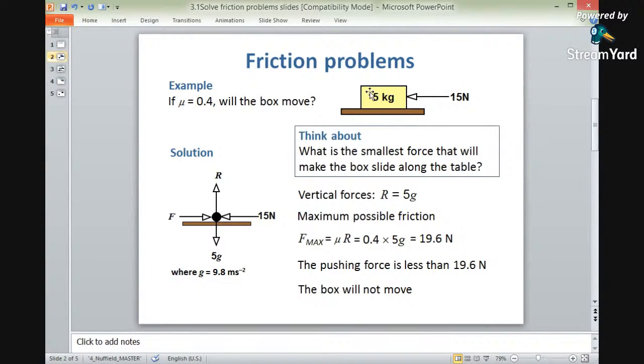Therefore, we have to draw the free body diagram for this block, which is kept on this table. The 15 Newton force acts as it is here, and here there is a contact surface. Perpendicular to this contact surface we apply the resultant force, shifted upside. Here frictional force will be applied in contact between the block and the table. There is a resultant force, or the normal force, which is perpendicular between the two contact surfaces. This R has been transferred upside.